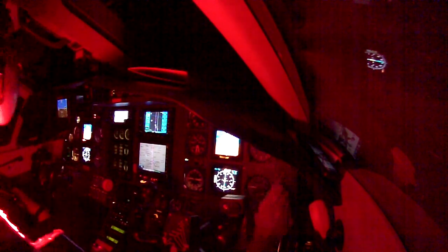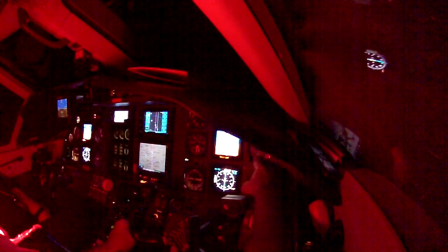Now, to the right of the HSI, what do we have? Altimeter. This is a mechanical type altimeter. It's got pitot and static, and that static provides altitude indication depending on your pressure altitude. Then you can select the altimeter setting in the window, and you have standard, and millibar on the left side.